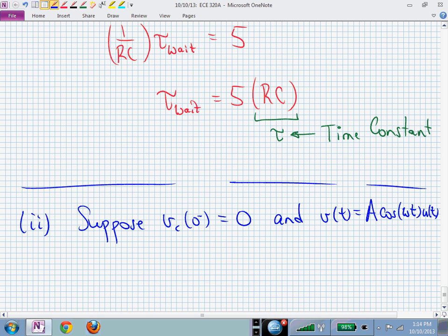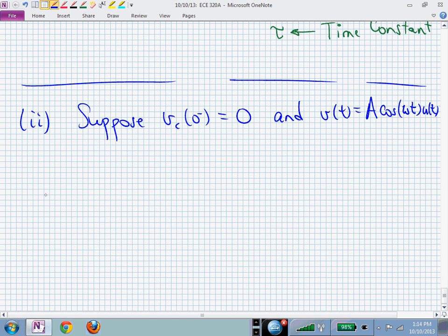So if you don't remember 377, you can go 2 pi. Oh, that's roughly 6. So 6 times 60, 360. You're in the ballpark, right? 360, 377, that's pretty close, give or take. That's pretty good, okay? 377. But we could pick that omega to be whatever we want. Whatever it is, what is our Laplace transform of that little v of t? Now you just go to your table, right? Table 12.1, and you find, in the time domain column, you find this cosine.